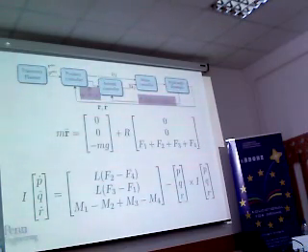At every time we can measure these parameters. We have the roll, pitch, yaw, and we have their derivatives. So these values will feed back to the controller in order to calculate the desired command in order to make the error tend to 0, for the roll, pitch, and yaw angles and the angular rates.